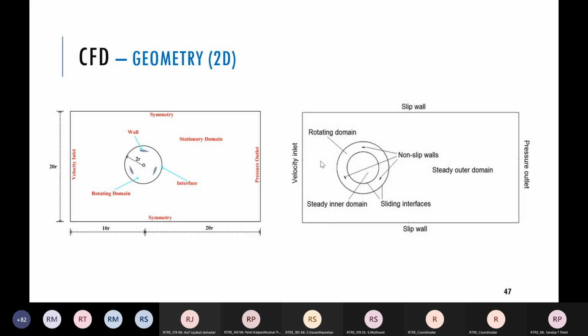Recently, people are not doing steady state analysis. Transient analysis is preferred, which varies with time. In this one, we are defining a moving domain. So the rotor domain is moving, rotating. Fine. So there are two meshes we generally define: a stationary domain and a rotating domain. The rotating domain is basically a circular shape in which the airfoils are cut. To further optimize, we can keep the rotating domain in a ring shape.